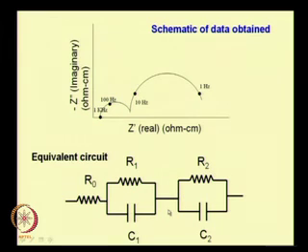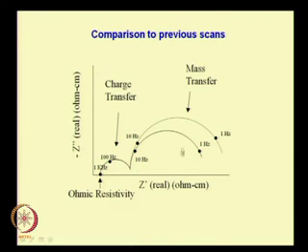One other way in which we could, even if we did not have an RC circuit, even if we did not do an equivalent circuit, another way we could do it simply is, as I mentioned, study the same system under different operating conditions. Let us just say under 2 different temperature conditions or 2 different humidity conditions, and you may see that in one case this is your AC impedance data and in another case this is your AC impedance data.